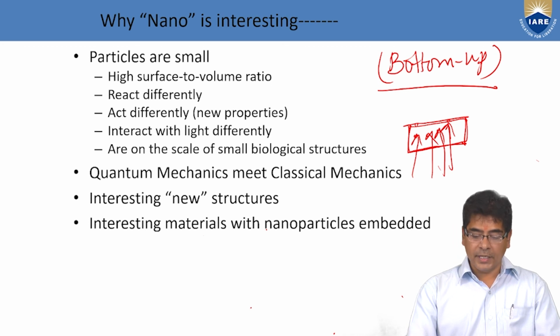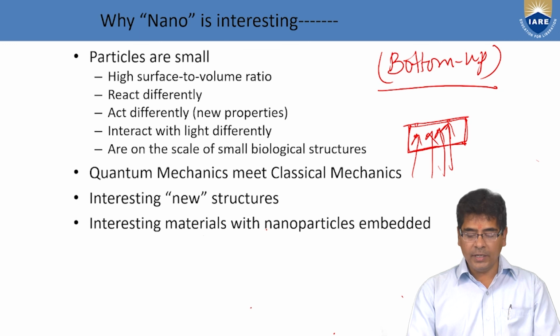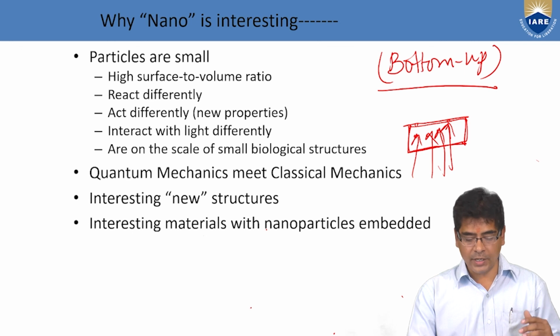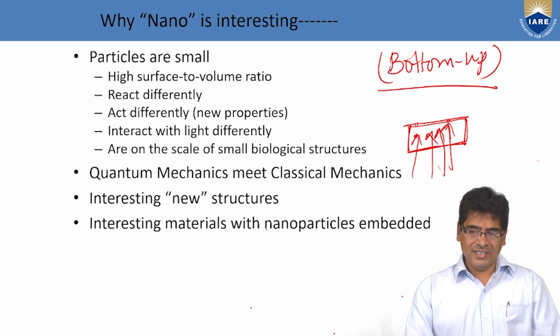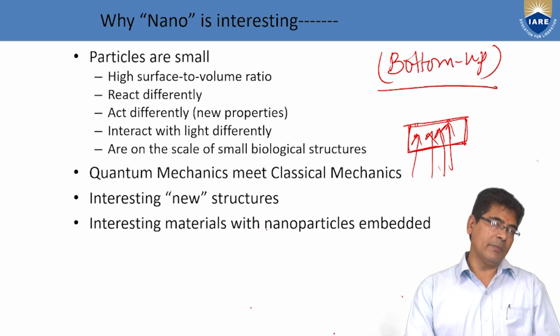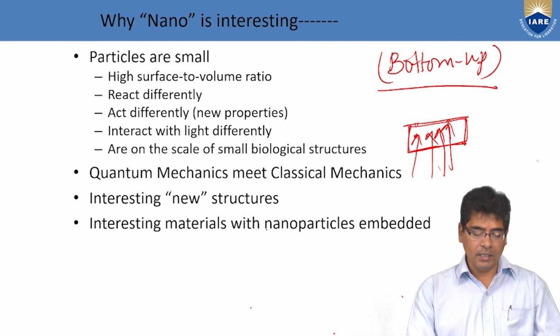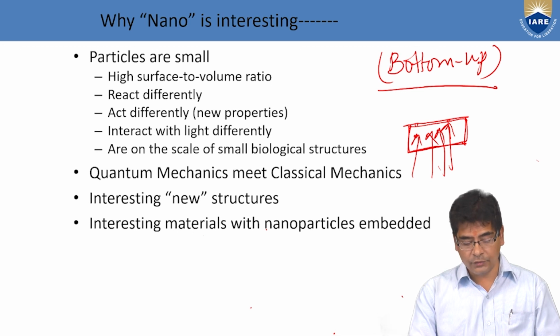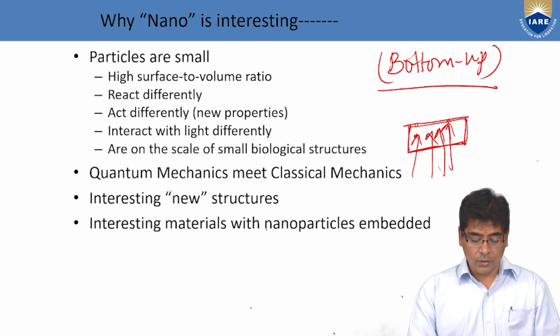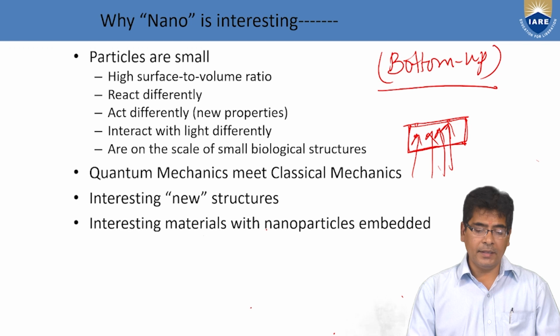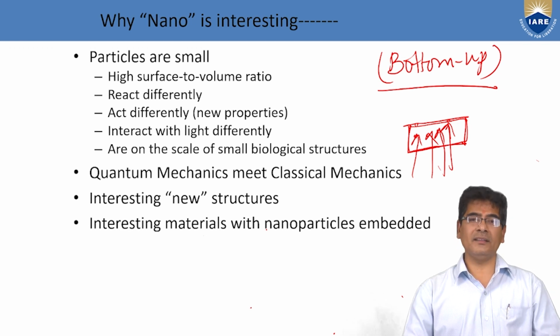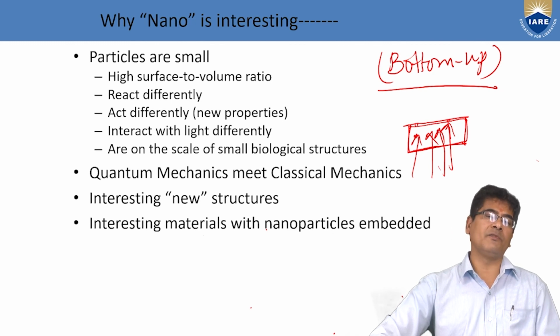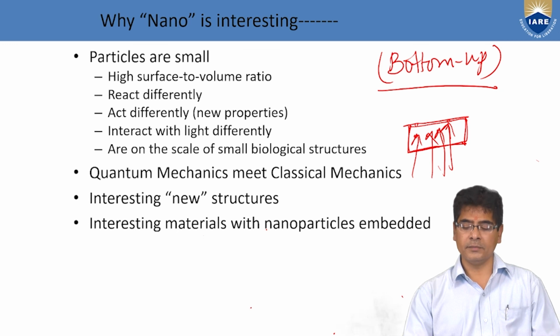In chemical vapor deposition techniques, CVD is widely used for depositing thin films for a large variety of materials. Applications of CVD range from fabrication of microelectronic devices to the deposition of protective coatings. In a typical CVD process, reactant gases at room temperature enter the reaction chamber. These are some of the fundamentals of how we can go ahead with the fabrication of nanomaterials.